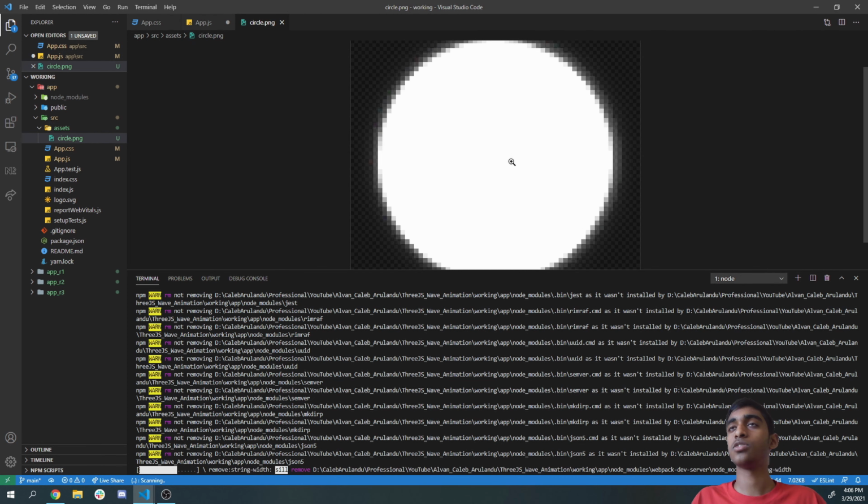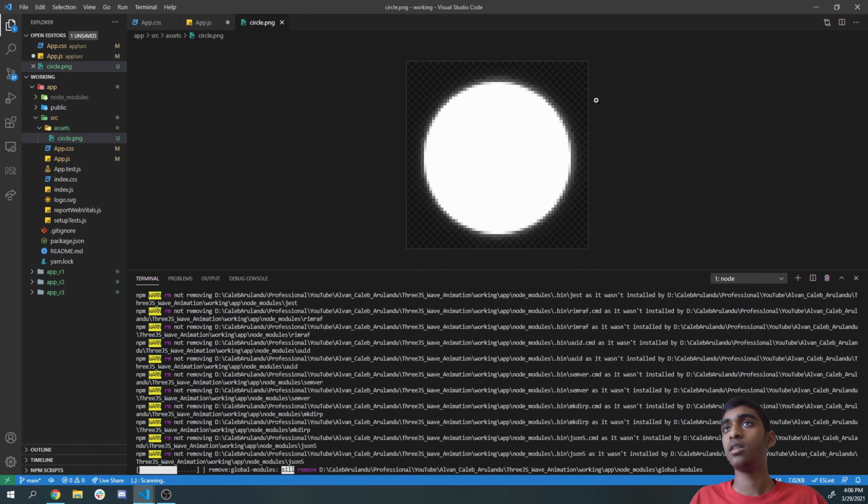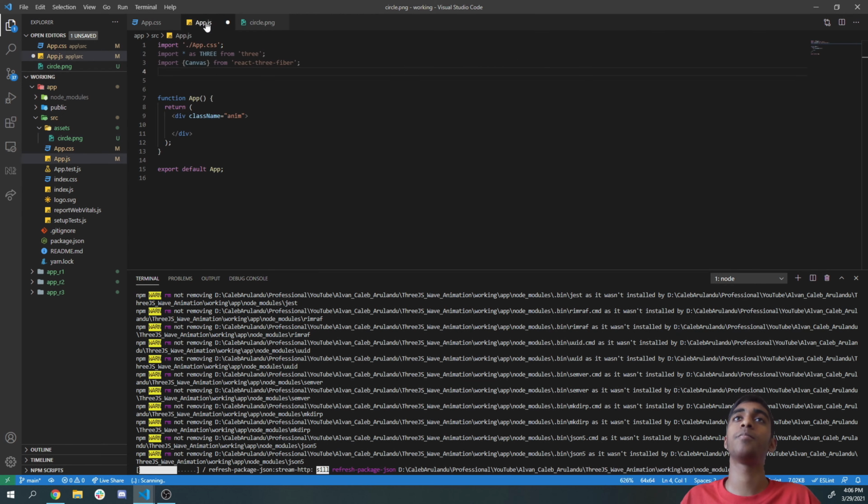And I also want to use an image asset, which I'll drag in right now. It's literally just a circle with a transparent border. The transparent border is important. You can really use any image you want, but this is what we're going to be using in our material to render each point. The only thing that's really important about the exact image, when used in the texture, is that it should have a transparent background wherever you don't want it to be visible. So if it's just black, the black is going to show, so make sure it's transparent.